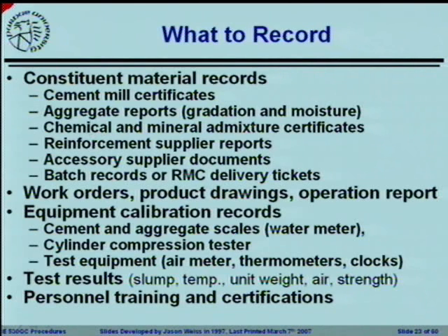Chemical and mineral admixture certifications, as they're coming through, they should be kept on file. Reinforcement supplier reports, just like we'll see cement mill certificates, you'll get the same thing for reinforcing steel. Any accessories that you're putting into the concrete. Batch records, ready mix tickets.